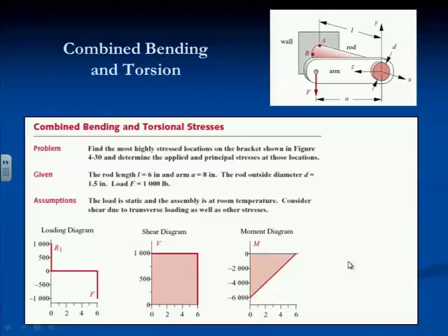So that's essentially all I need to analyze the beam conditions, because I need the shear and the moment. But I also have a torque. And that torque exists all along the tube because I'm out at the open end of the tube at L, putting that force on with a lever arm, which is that distance A, and that creates a torque in the tube. Now, of course, the wall is resisting that torque with another torque in the opposite direction, right? So much like the V diagram, it looks just the same except the numbers are different.